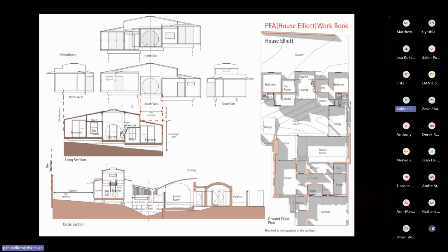In zoning, you can only go to the boundary for a certain length of the perimeter wall if you are in a setback of 3 meters and under a height of 4 meters, which is satisfied on the northwest side, and on the east side allows me to gain this extra space for the loft that I showed you in the photos.